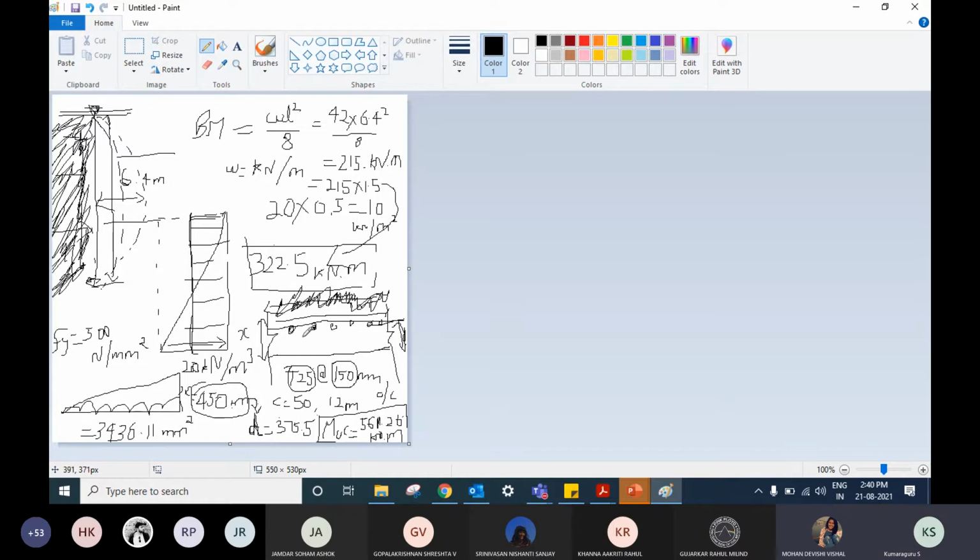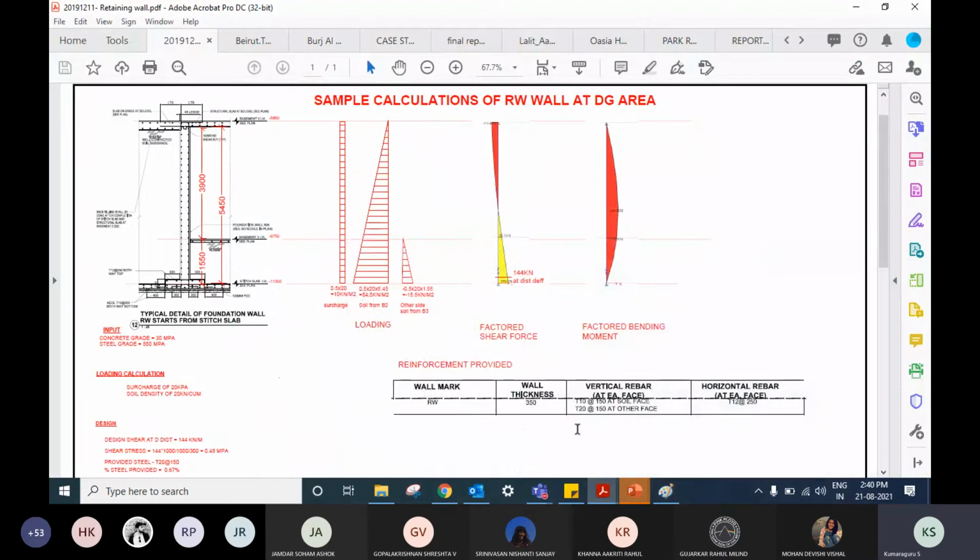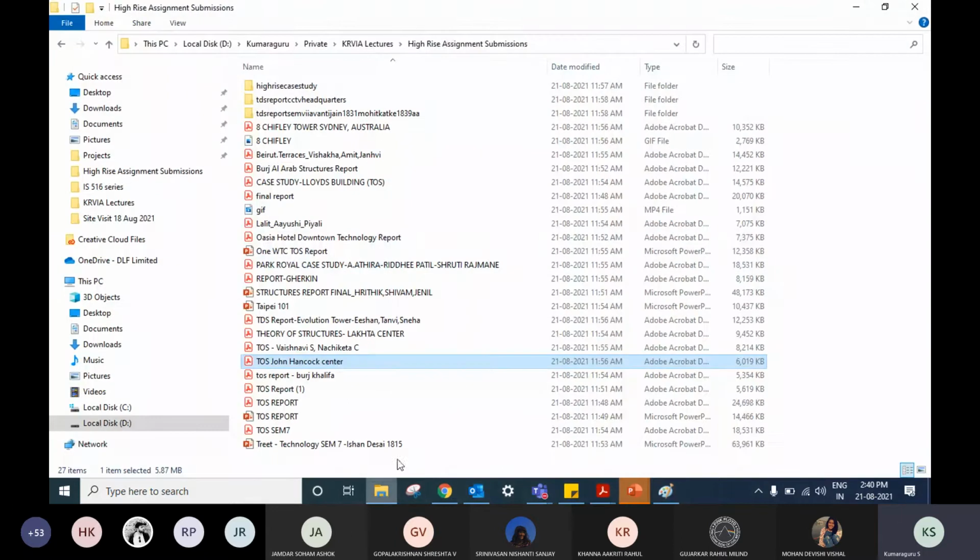Right, okay. Your question was, so we understood, we came up with the section, right? We decided what thickness it should be and what rebars I'm placing, and I found the capacity of that section. So if this is way too higher than my demand, I'm going to change the diameter or the spacing, or reduce the cross section and see what happens. After this, the next step is final detailing.